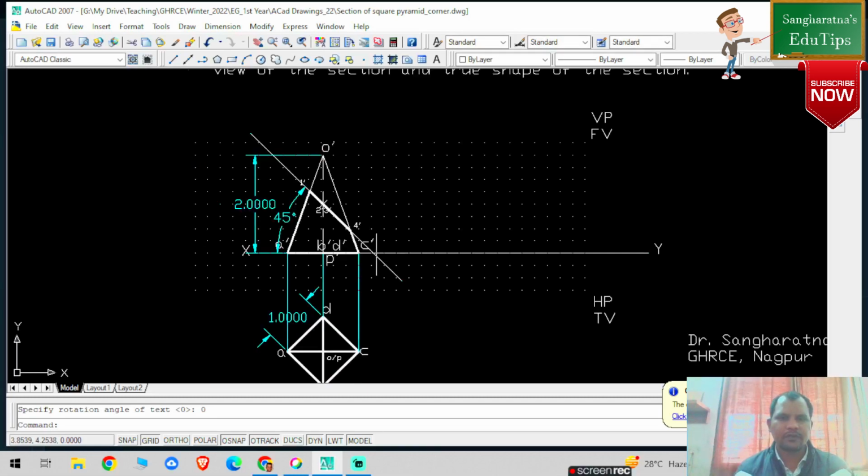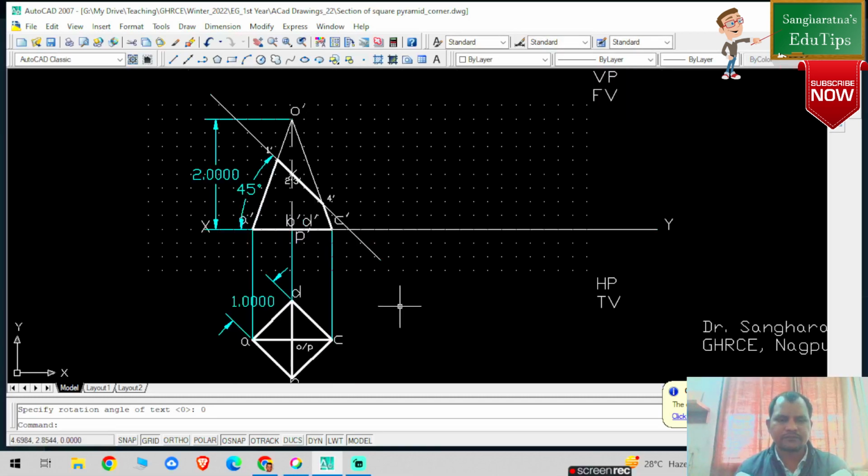Now from this particular line I'm going to draw the projector lines on the particular edges. I'm going to select a line here, selecting ortho as well. From this point, one will be on the OA line, so it will be cutting here.